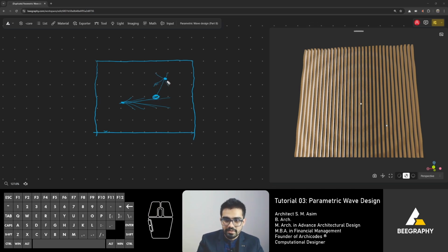So all these points should ideally consider this distance, and that is what closest point does. It identifies which attractor point it is closest to, this one or this one, and then takes only that value and eliminates the other value, and that is why we get a nice cohesive attractor point logic with multiple points.